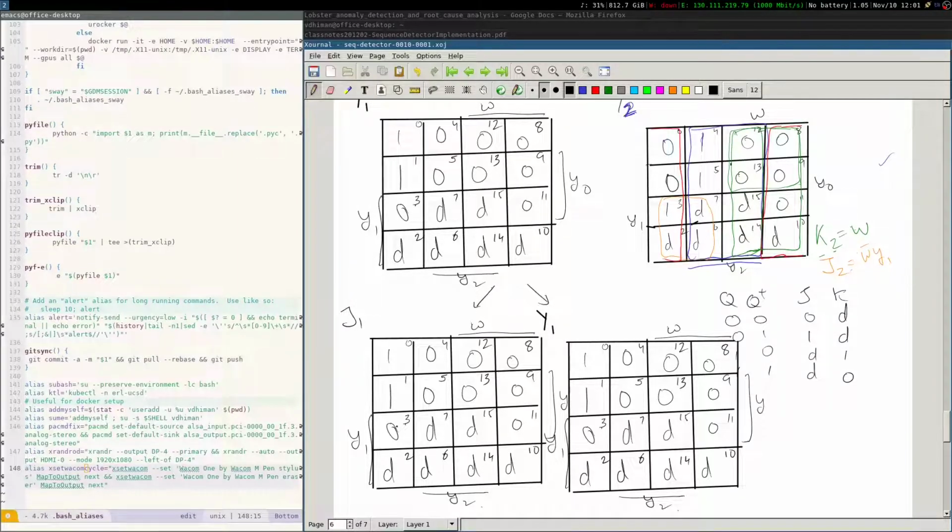For the K1 map, where y1 is 0, that becomes don't care, so all of this half of the K-map becomes don't care. And wherever there was a 1 or 0, zeros become 1, ones become 0.